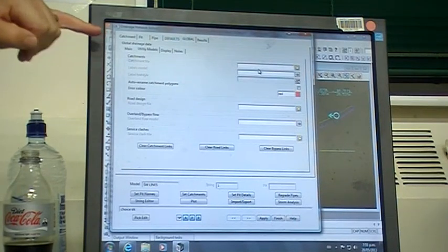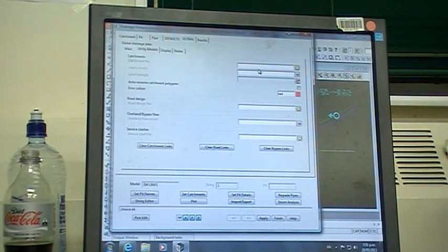Okay, the catchment file is just a file so that when all the polylines that I've drawn within that catchment file, when I hit set catchments, it will try and assign the nearest area that I've circled to the nearest manhole, so it tries to work out what we're trying to do as far as the reticulation goes. That will all become evident when we start to play with it.